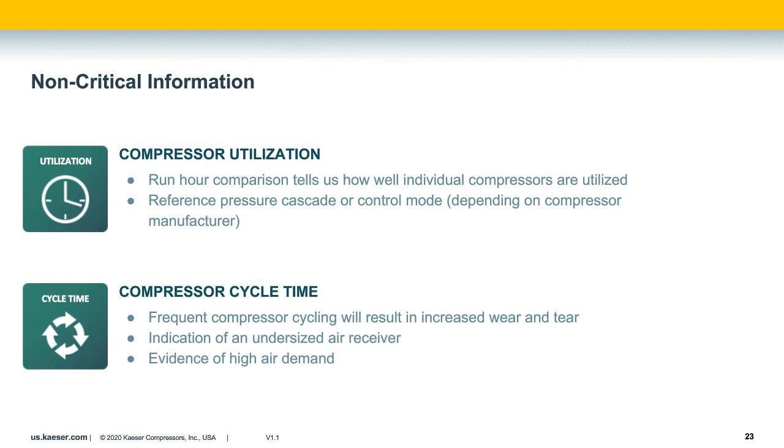And last but not least is compressor cycle time. You could also talk about this as duty cycle. Frequent compressor cycling will result in increased wear and tear, and therefore is a good indication of how well or how poorly a system is designed.